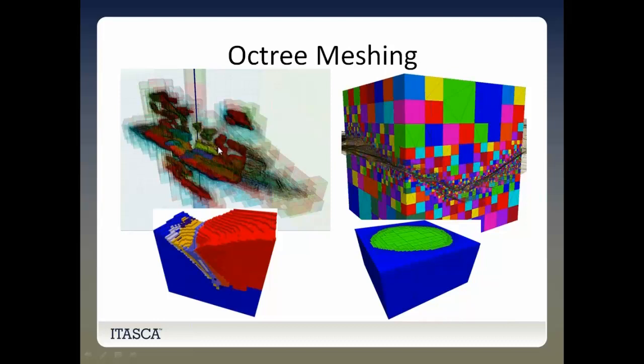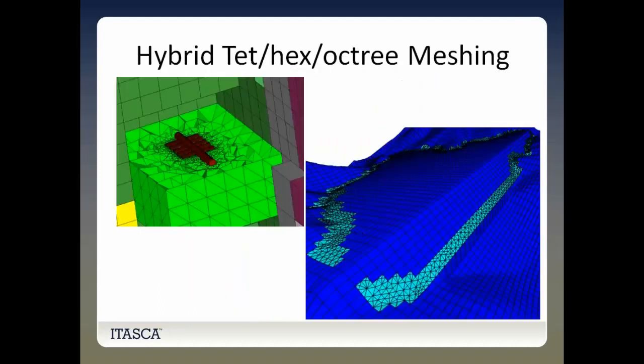So this step-by-step approach of coarse zones that become finer and finer as we approach a certain detail is an acceptable and a very efficient and extremely fast way of generating models without needing even to clean up the geometry. The object does not need to be closed. It would have overlapping gaps and so on.